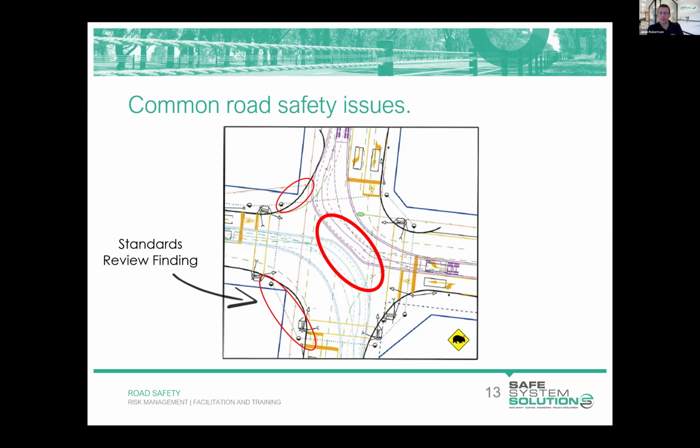That's right. And I said I was going to come back to check vehicles, didn't I? So the design vehicle, certainly you want to design for it to be able to make its turns from the correct lane, and remain on the pavement. The check vehicle, as Ken mentioned, is that larger vehicle again that might come along once in a while. And because it comes along so infrequently, we don't design our roadways to cater for that vehicle particularly. We accept that it might need to swing across into the opposing lane to make a turn.